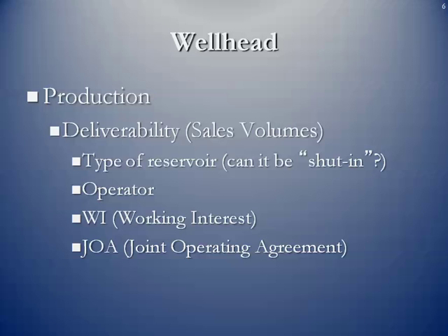So we're going to start at the wellhead. This is the production. This is what we're interested in. Once the well is completed and starts producing, we're interested in how much volume can be sold on a daily basis. This is known as the deliverability. Now, this depends on the type of reservoir that you have. Some reservoirs, once they start producing, cannot be shut in. That is, they can't be turned off because you can actually lose the production.